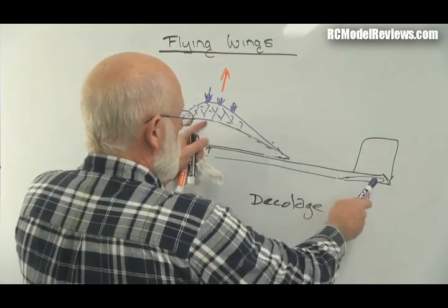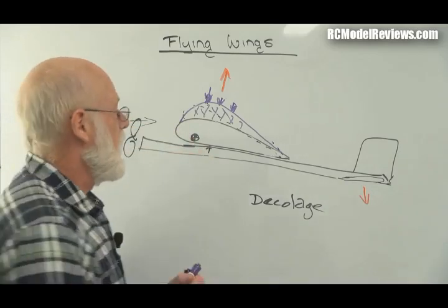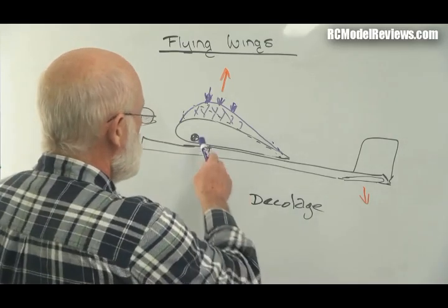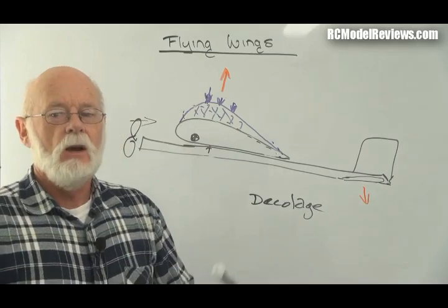That's the difference between the two angles of the wing and the tail plane. That gives us our pitch stability. Simple as. And that's why we also have a forward CG. Now, you may realise, remember, if you move your CG back, your plane becomes unstable. We all know that. You will try to fly a plane with a rearward CG.